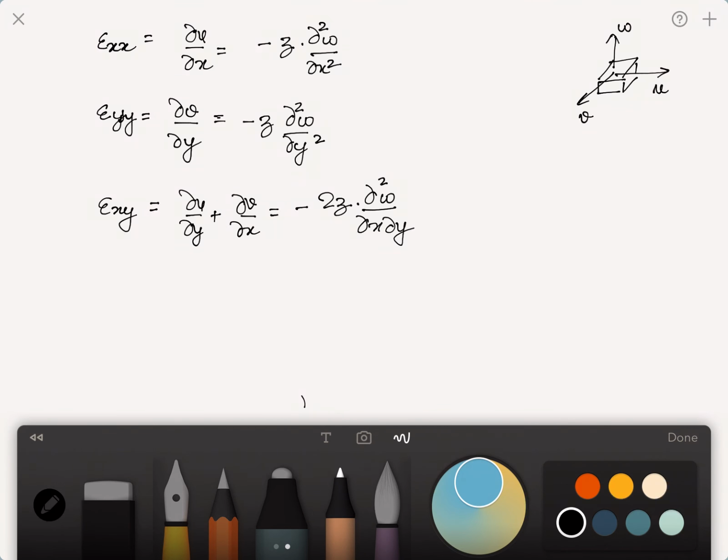Okay. You can also derive all other relations. You can derive the moment relations and the stress strain relations given the moment, etc. And you can go on and describe the entire bending plate theory just by making use of these dependencies. And of course, if you have a rotation, then it is a partial derivative of this out of plane displacement w, which you have already seen in the case of a beam element which has transverse displacement and rotation at its nodes.